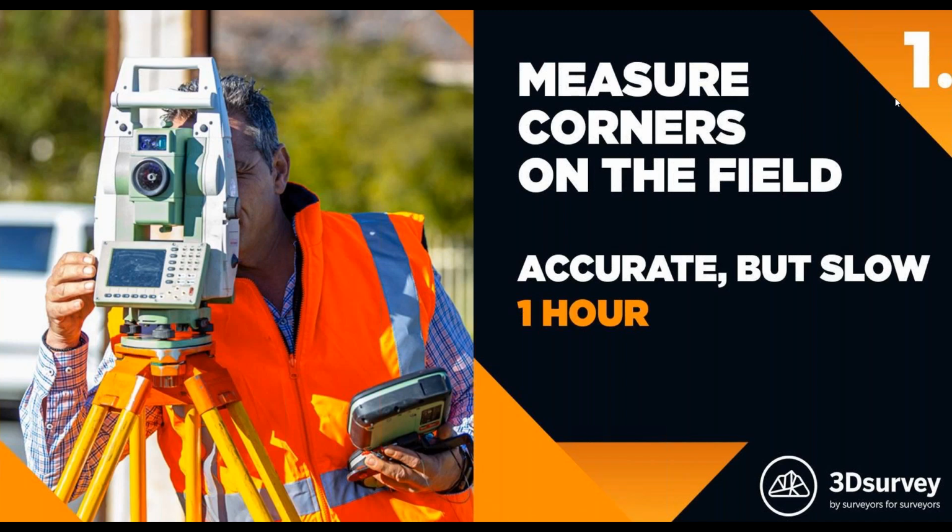This method is very accurate, but it's also time consuming because we have to go to each corner and measure it. We also know that you have to know what you are doing and have a special technique for measuring it, and the accuracy we can expect for the building corners this way will probably be around 4 centimeters.